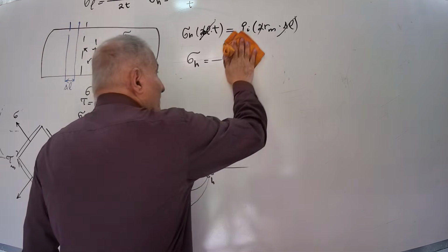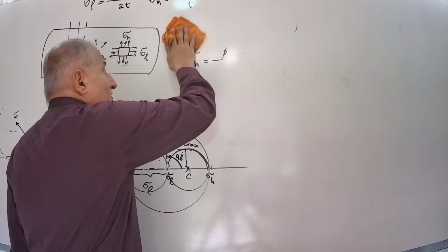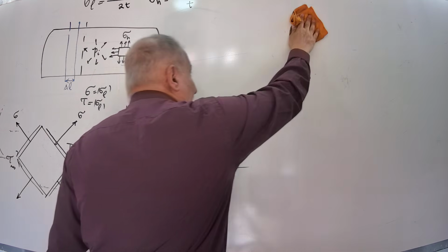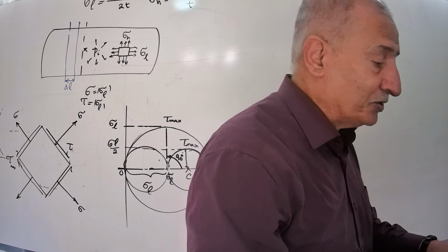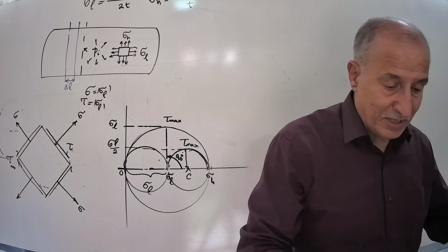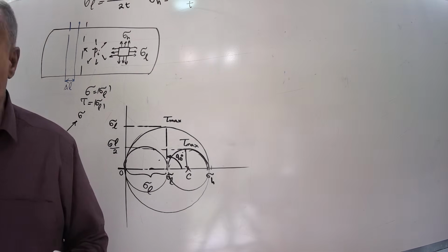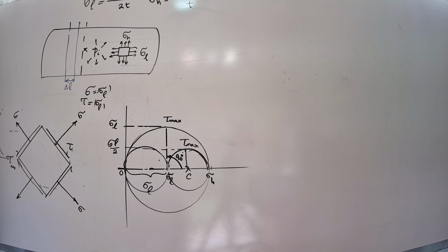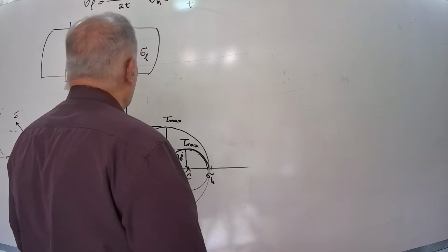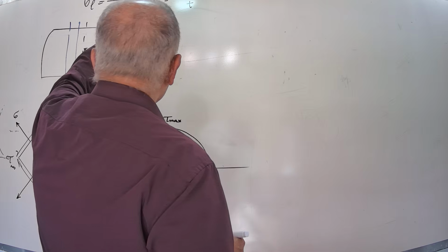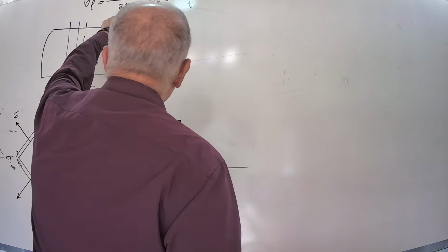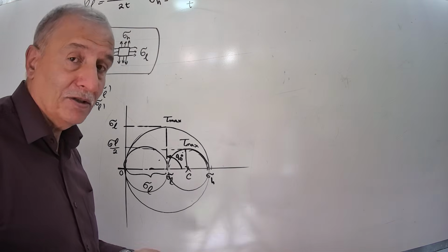Okay, let's consider the ASME code for designing pressure vessels, and see from what source they get the formula. In the ASME formula, they design for thickness because the material is known.